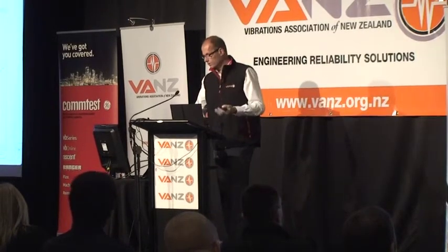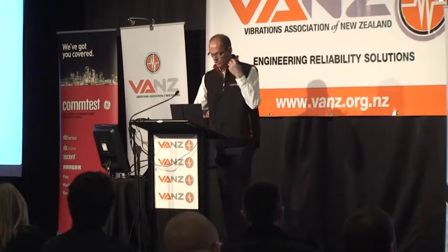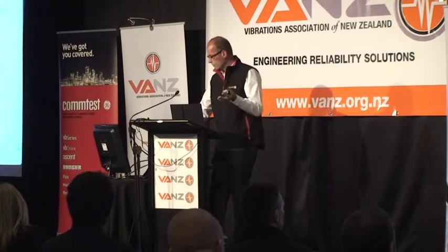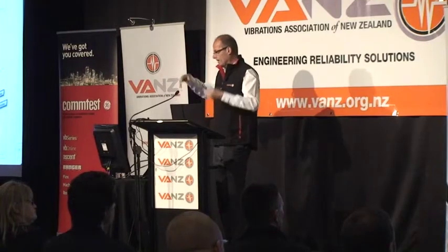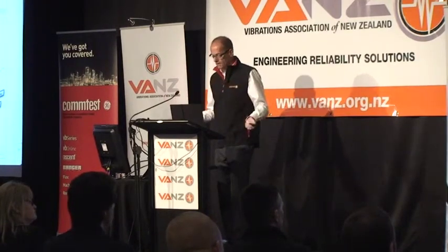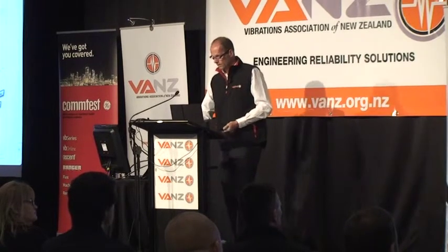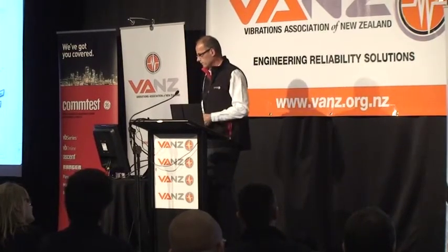But from that point on, we can say that the condition will be degraded. The condition will go down and down. And if we don't do anything about it, we'll get to a point where it will catastrophically fail if we did absolutely nothing. But we can identify a point just before that where we call it functionally failed. And that F for functionally failed is the F in the PF interval.